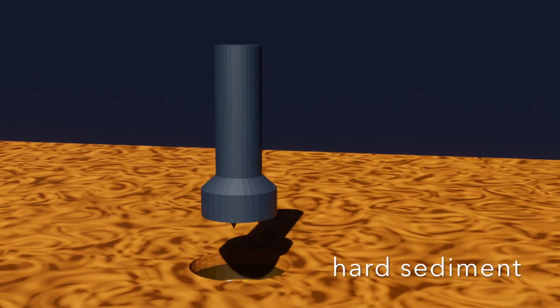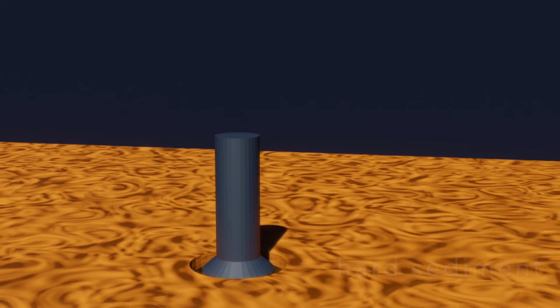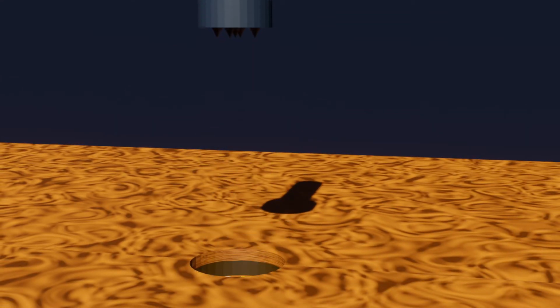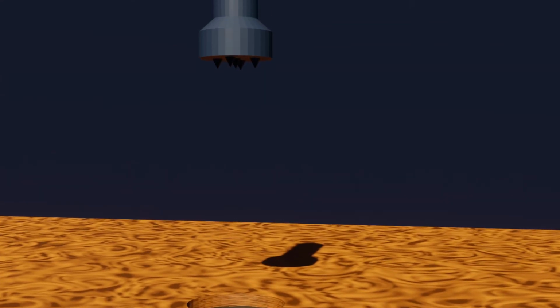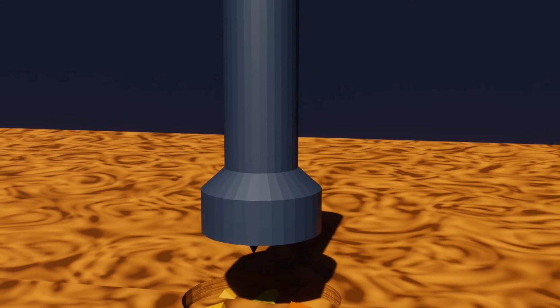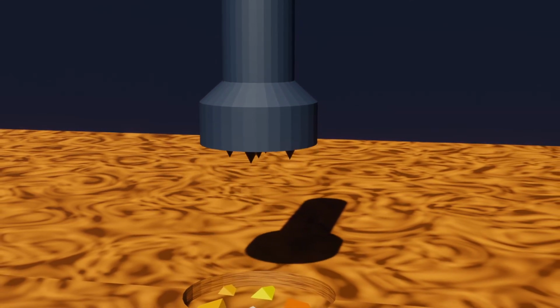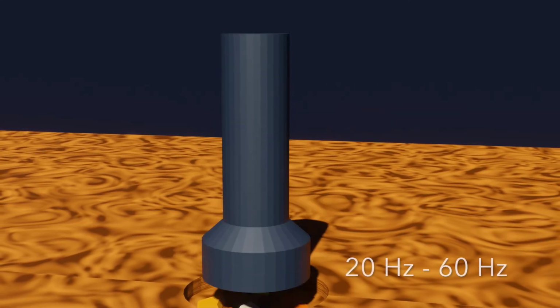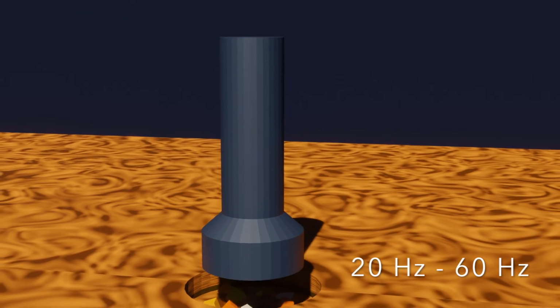The drill blows on the rock continuously. However, with each new impact, the bit is slightly rotated and a new point on the rock is being drilled. The impact frequency for percussive drilling usually lies between 20 Hz to 60 Hz.